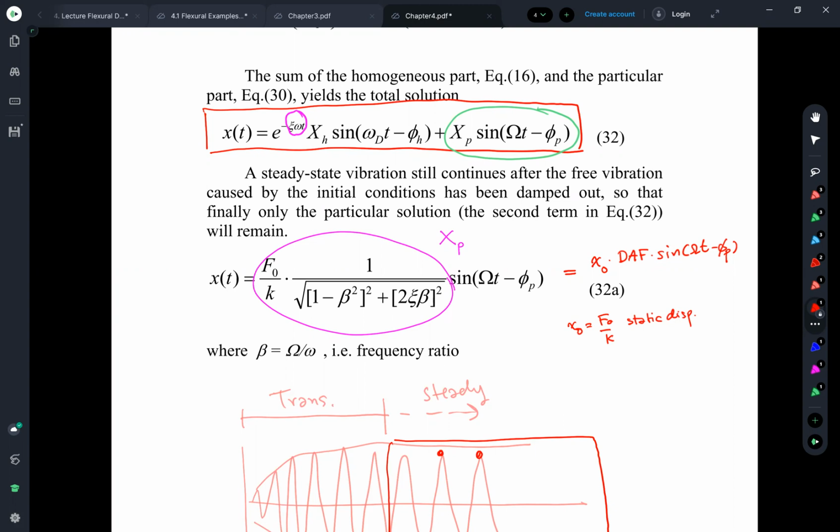For example, if I design a bridge under the American design code called AASHTO, they ask me to compute the term called the impact factor. And after I compute the impact factor, maybe the number I get is something like 0.3, 0.25.